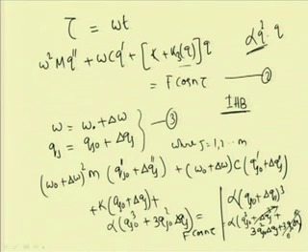The remaining terms, by neglecting the higher order increments, can be written in this form: omega 0 squared m delta q double dash plus omega 0 c into delta q dash plus k plus k 3 into delta q.